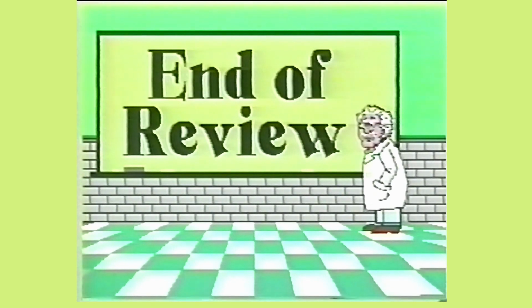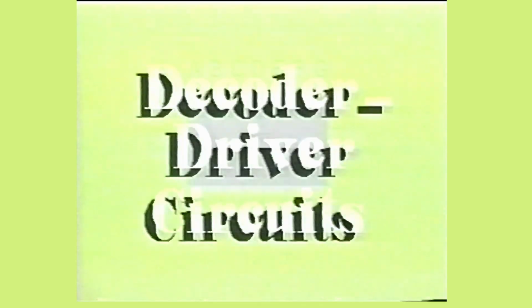Now that you have a basic understanding of how some of the common display devices work, we will next examine the circuits used to control these display devices. Before a display device can show a character, it must have a properly decoded signal being applied at its inputs. It must also have a device capable of supplying enough power to drive the display unit. This is generally accomplished with a decoder and driver circuit. These circuits may be individually packaged in their own IC, or they may be combined in a single IC package called a decoder driver circuit.